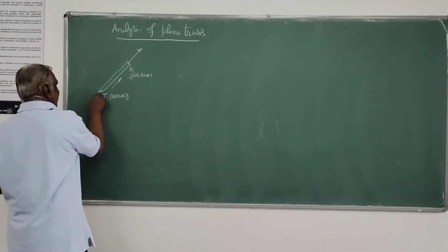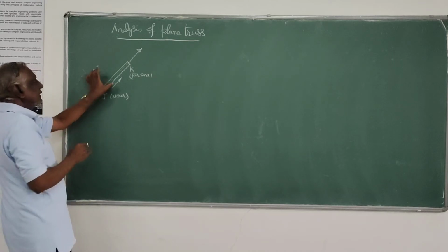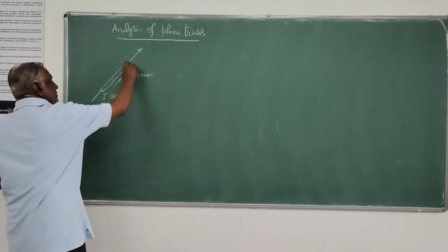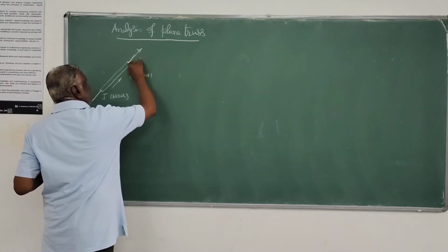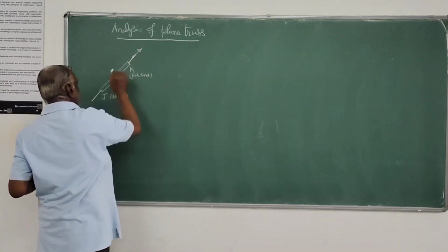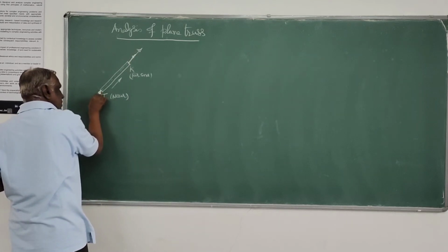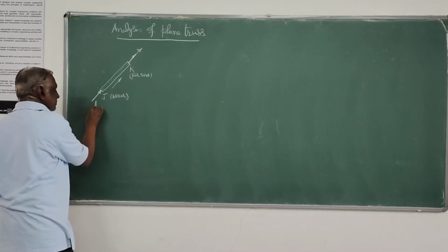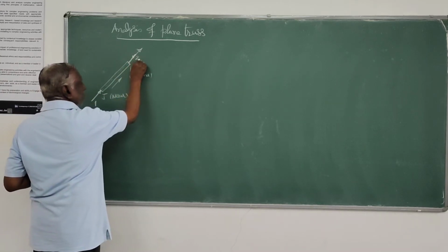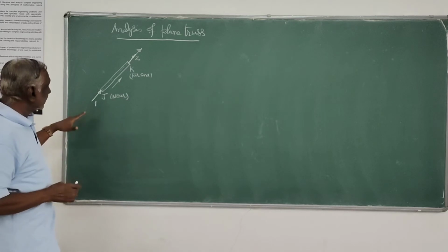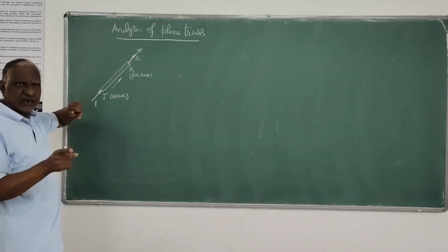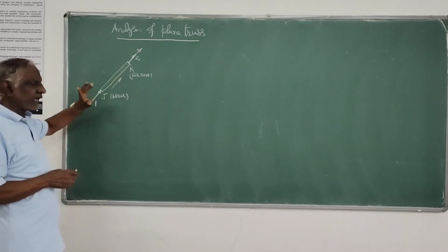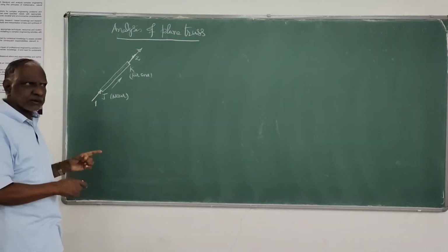And here, having defined that, the force in this particular plane truss is always axial force. That means force will be through the axis of the member, and displacement also has to be through the axis at the ends. This displacement coordinate we call as 1 and this as 2. Coordinate is the word I have used; it indicates the positive direction of either force or displacement.